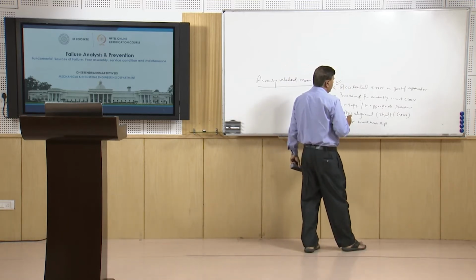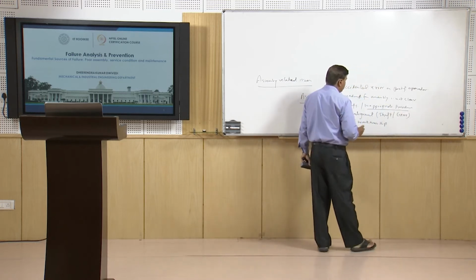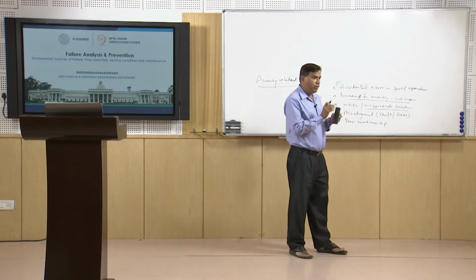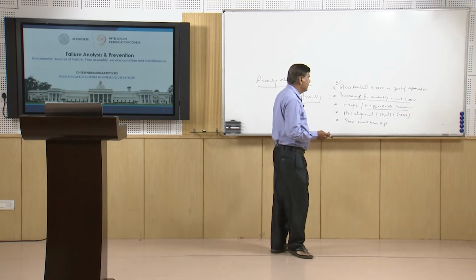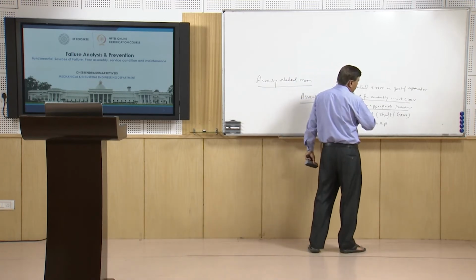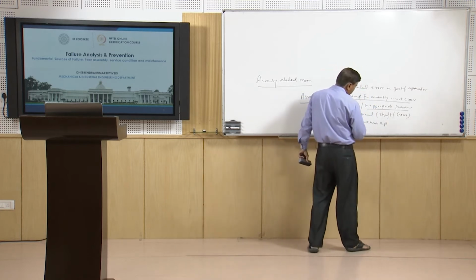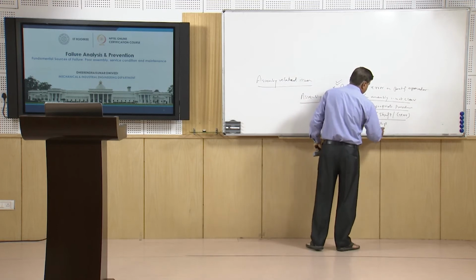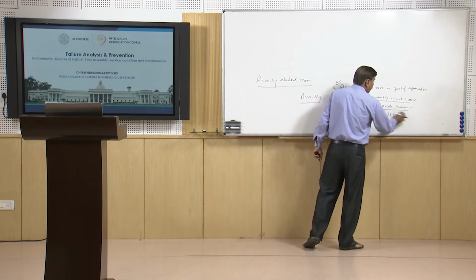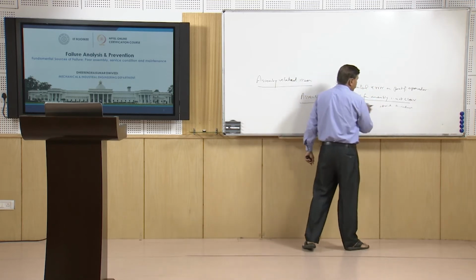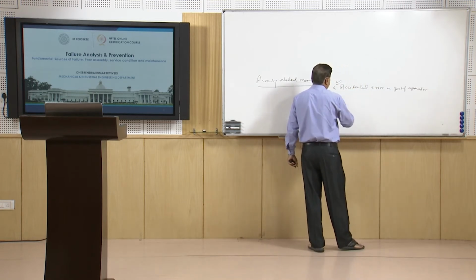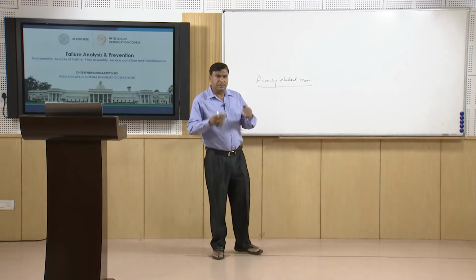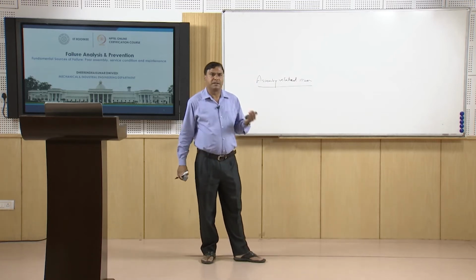So, more effort needs to be put in. A well thought out procedure for the assembly should be developed, and it must be made clear who will be doing what, how it will be done, and when it will be done. Misalignment has to be avoided, especially when relative movement exists between two or more components, and poor workmanship is to be avoided through proper training and awareness programs for the operators, so that they are more motivated towards the work and follow the instructions given for the assembly. These are some of the general reasons observed for failure due to poor assembly.